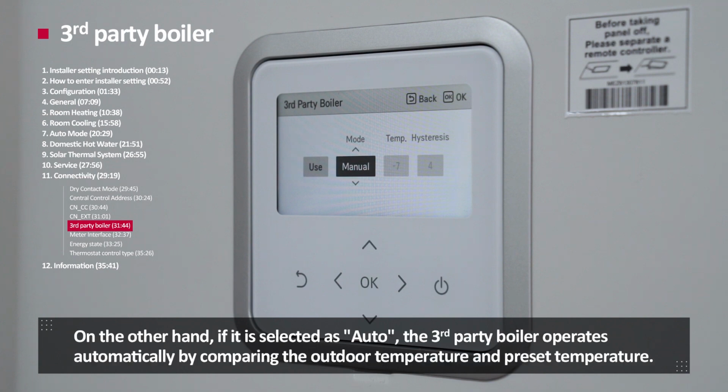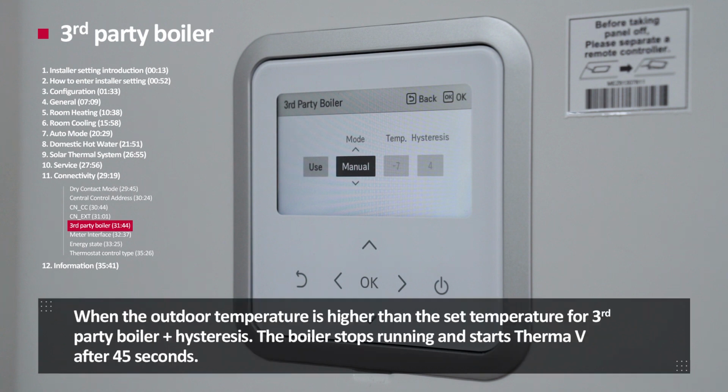On the other hand, if it is selected as auto, the third-party boiler operates automatically by comparing the outdoor temperature and preset temperature. When the outdoor temperature is higher than the set temperature for a third-party boiler plus heat status, the boiler stops running and starts Therma V after 45 seconds.